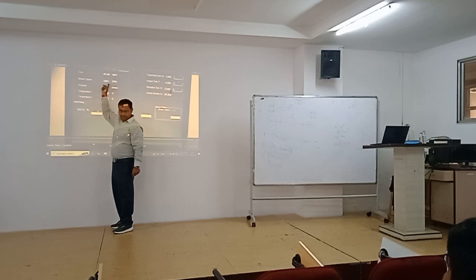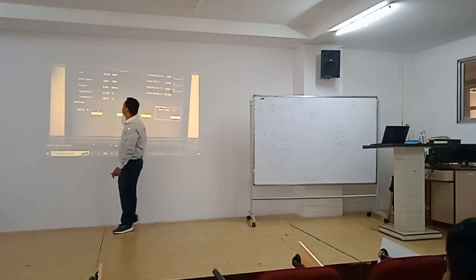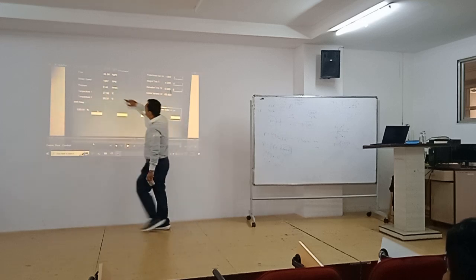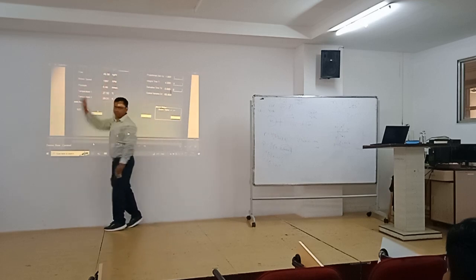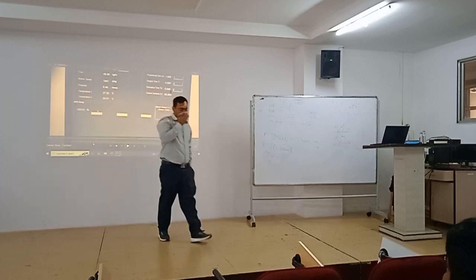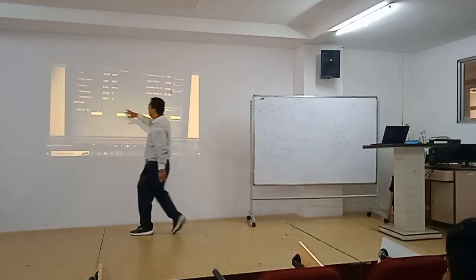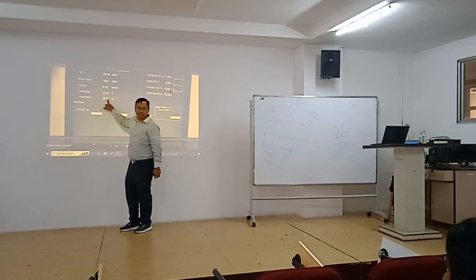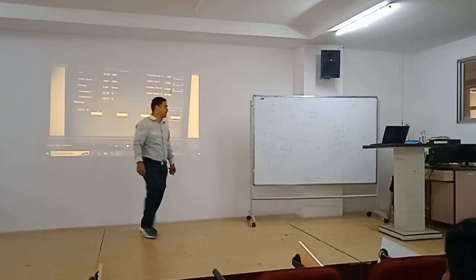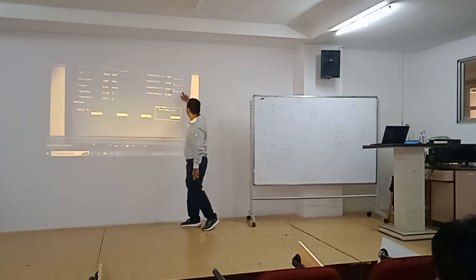Okay, it's on 1867 RPM, and flow is 49.88. Desired flow is 50 kg per hour. So now we are making the heater on, and you can see the temperature one is 27.80. Temperature is 29.31 degrees. So this first temperature sensor we kept here, near the blower.